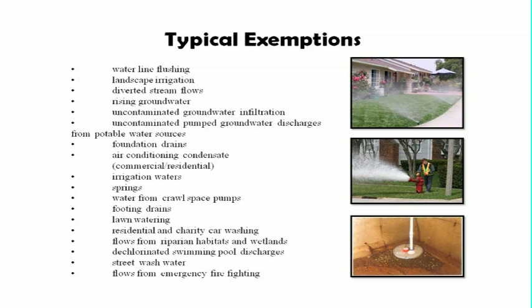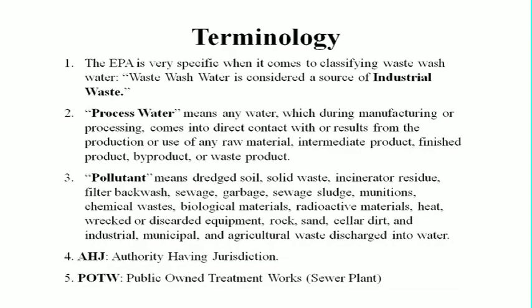But most places right now, it's not a significant contaminant, so the homeowner can wash his car in his driveway, but he can't hire a contract cleaner to come in and do it and run the same wash water down into the storm drain. If a contractor comes in, he's going to have to capture that wastewater and discharge it appropriately. Hopefully, that will be to the sanitary sewer.